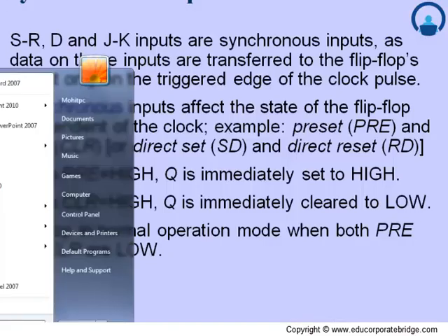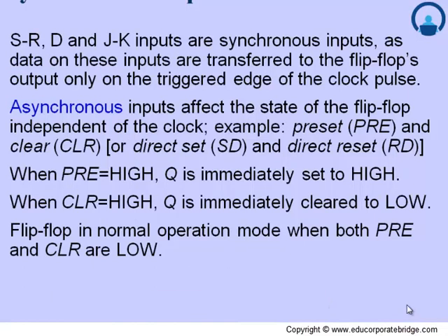Asynchronous input. Let's study how we can work out the asynchronous input. What exactly is the meaning of asynchronous input? As we can see from the theory, SR, D and JK inputs are synchronous inputs, as the data on these inputs are transferred to the flip-flop's output only on the triggered edge of the clock.